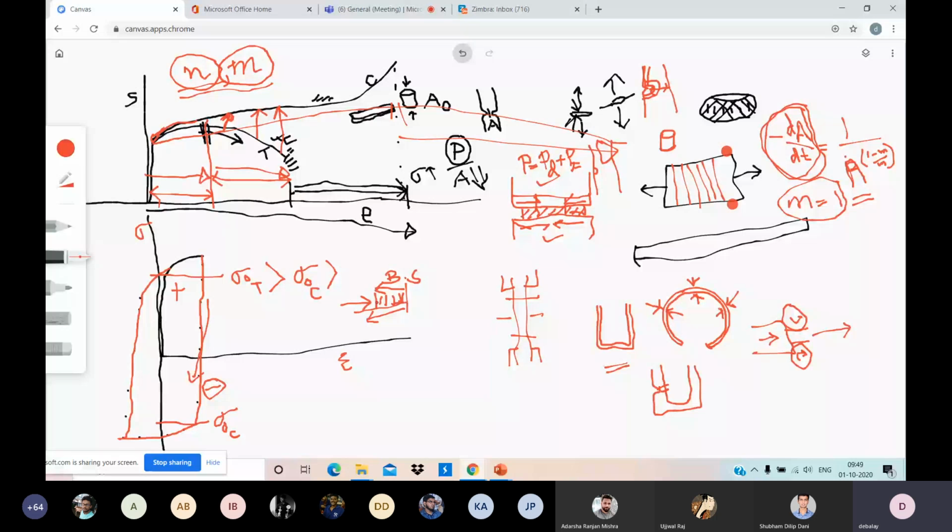If you apply loading in one direction and if you reverse your loading, then the strength goes down. And again you do reversing, continuously it will go down, up to a point where this thing stabilizes. That is called stable hysteresis. So what I am showing, there is a hysteresis loop and it will stabilize at some point, which we call stable hysteresis. In fatigue, these things happen.